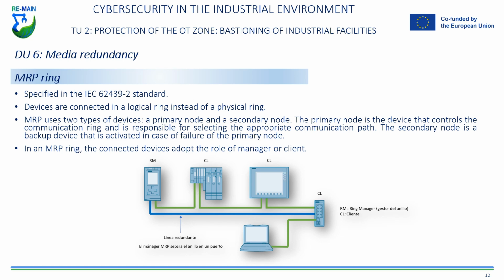In an MRP ring, connected devices take on the role of either manager or client. Managed switches can have both roles. Decentralized peripherals can only be clients. PLCs can have both roles. HMI panels can only be clients.